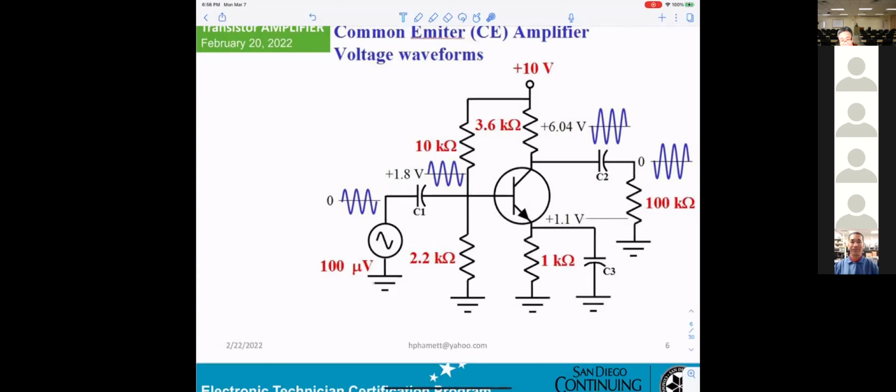However, if you want to measure the peak-to-peak voltage here, what will the oscilloscope be set to? You understand, on the oscilloscope, you can set DC coupling and AC coupling. So if you want to measure peak-to-peak voltage at this point, which one will be set?